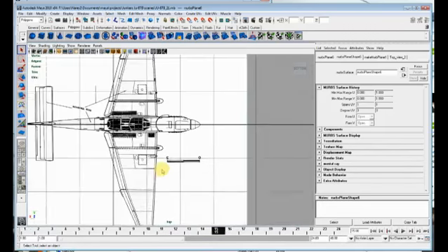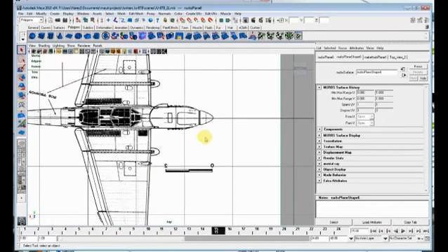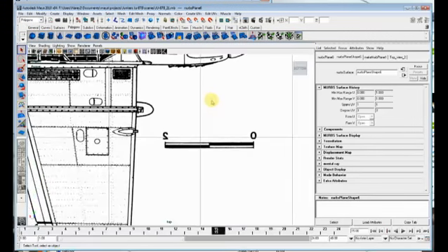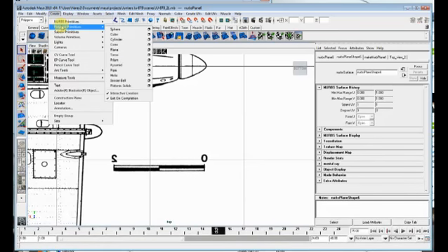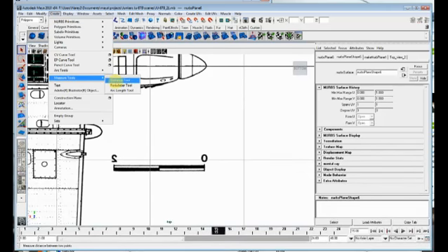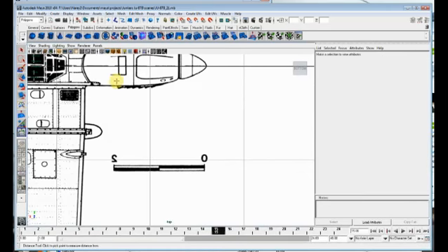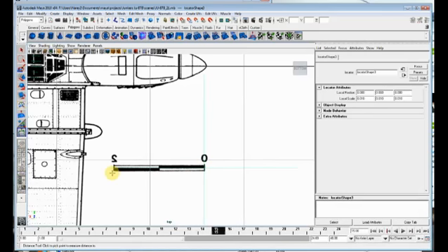But once you're on the proper metric scale with these squares equaling 1 meter, you go down here to the scale on your blueprint and you go up to this Create tab, and instead of creating another plane, you create a measure tool and you create what's called a distance tool. Now before you set anything down, you turn off your grid snaps and you go down to the metric scale, and at the first one click on the 0, and on the second one click on the 2.